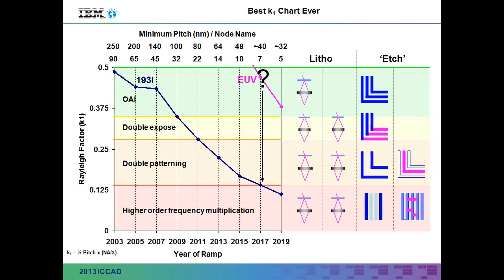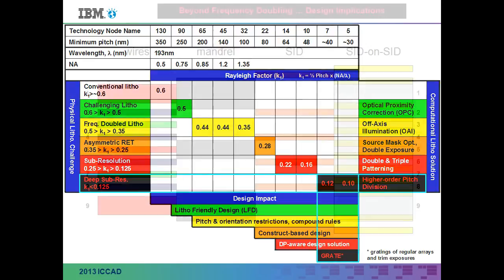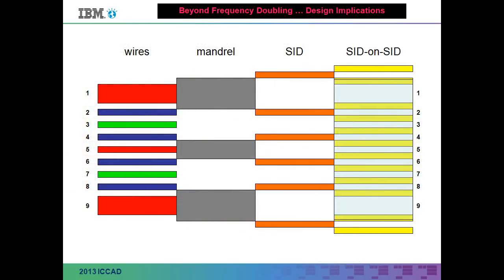We certainly plan to use EUV. We would like to use EUV, but what if it's not ready, right? What do you have to keep going? So I already showed you self-aligned quadruple patterning. I spent an afternoon trying to figure out what design rules for this thing would look like, right? So here's a simple drawing, right? I'm trying to make a couple of wires, say, some power rails and some signal wires.